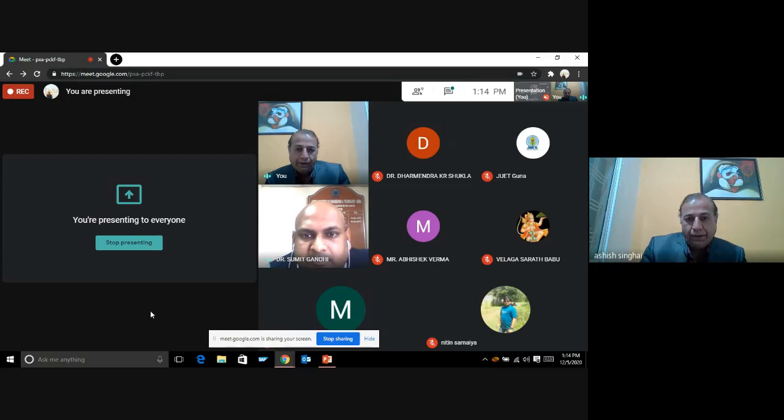See, in the code provisions also, a certain percentage of dust is allowed. It's not a big deal, but the effort should be to minimize the dust content because ultimately it increases the water demand for the concrete. The more dust there is, the more water will be required to coat those tiny particles. So dust has to be on the lower side.